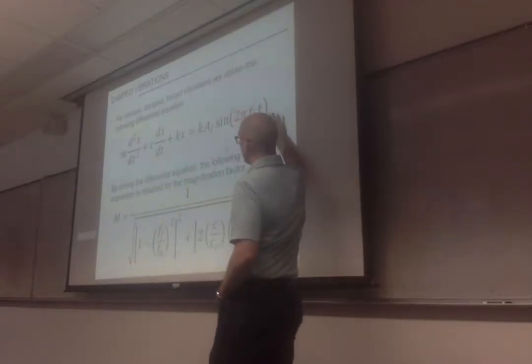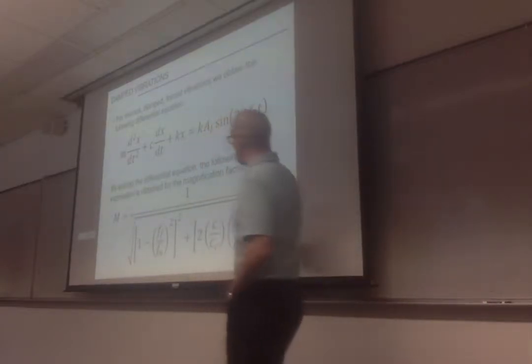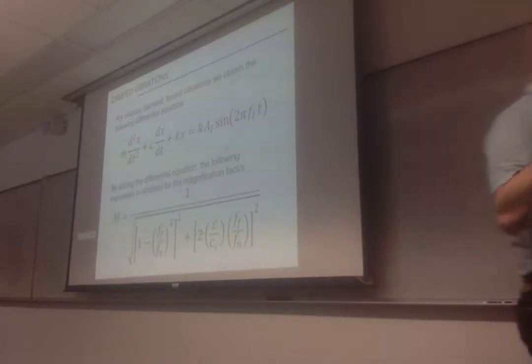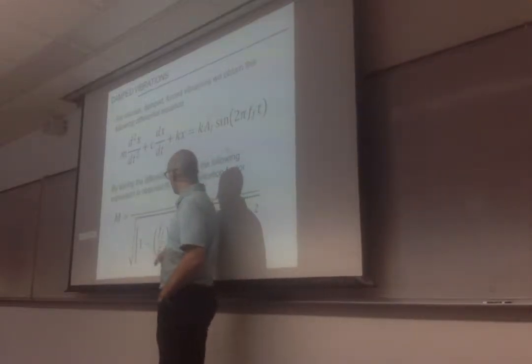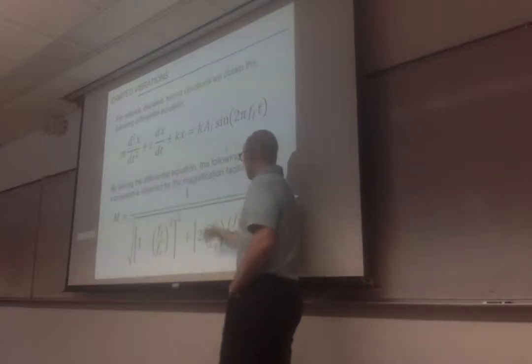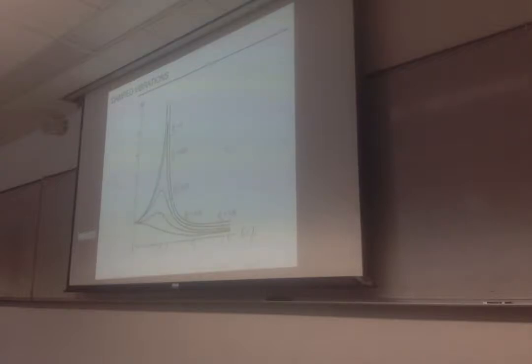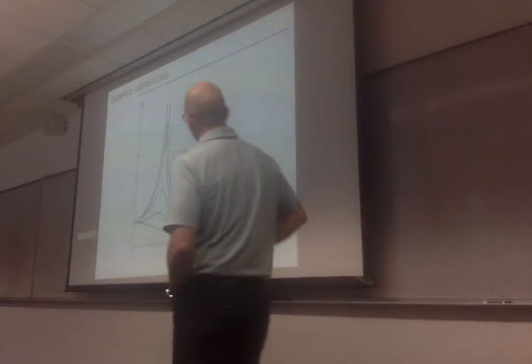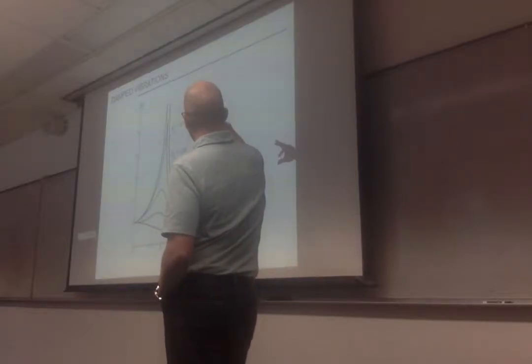If you were to work out this solution, you can establish an expression for the magnification factor, or sometimes called the amplification factor. In this equation, you'll have the classic natural frequency we talked about, the forced frequency, and the damping that plays a role here. Now, if you look at this equation and plot it, it should be understood that this is the absolute value of the magnification factor.